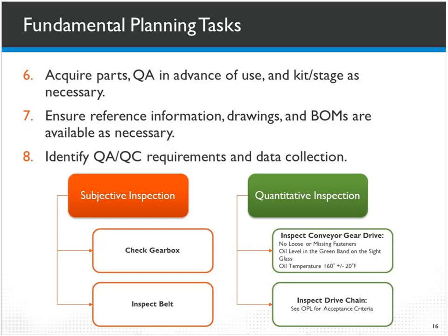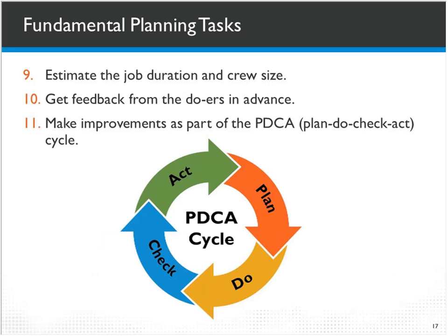The QA/QC requirements, these are the specs that you have to go from the subjective inspection to a very quantitative one and write down the torque specs and write down which particular type of grease is required in this application and how much grease. I mean, you have to be specific or variation will follow and people will do things different ways and you've lost the prize of reliability at that point.